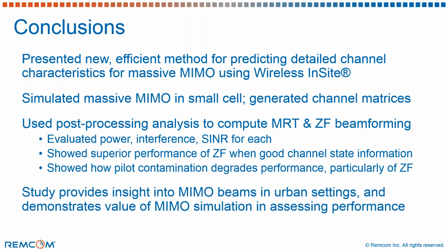This study has demonstrated the MIMO capability, and it provides some insight not only into what MIMO beams look like in a complex urban setting with a lot of multipath, but it also shows the kinds of things that you can look at when you have a good MIMO simulation capability to help you assess beamforming solutions.